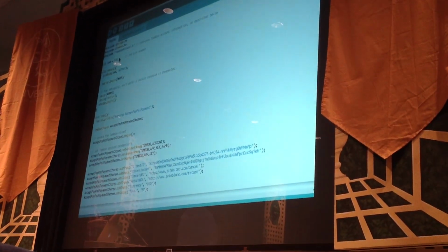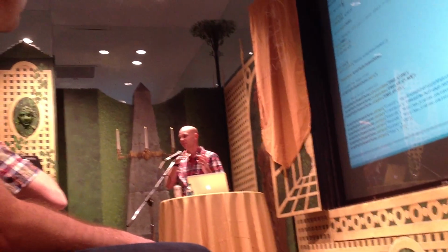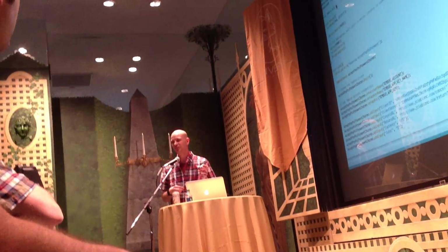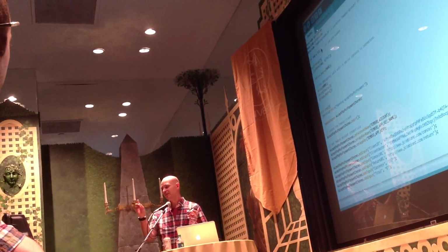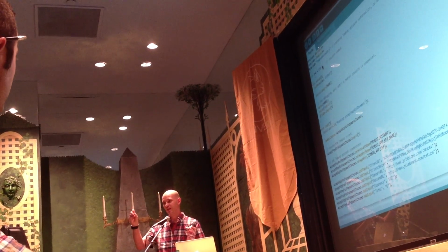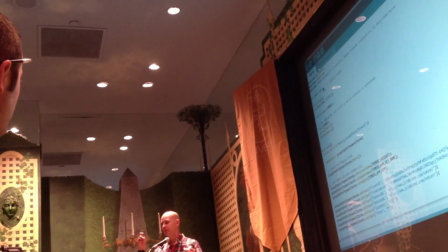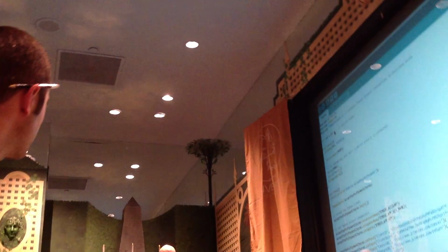All right, so we have a pin. There's a long one and a short one. We connect the long pin into digital pin 13, and the short one into the ground. Now, obviously, if you connect this into, let's say, a breadboard to do more extensive hardware implementations, you can plug this in anywhere, but essentially it's long for the actual digital integration, and then the short one for the ground. So we're just going to plug this in and make this easy on us.